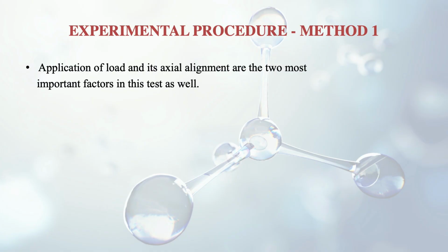Now we will discuss the experimental procedure. How do we do the compression test, whether it be ductile material or brittle material. Very important in this is the application of load and axial alignment. So the application of load and axial alignment are the two most important factors.